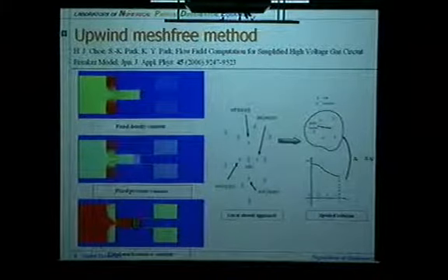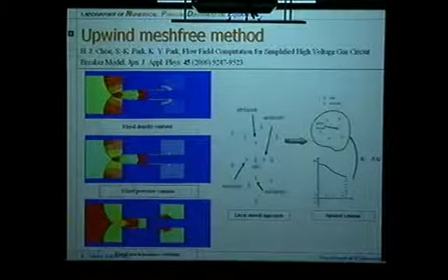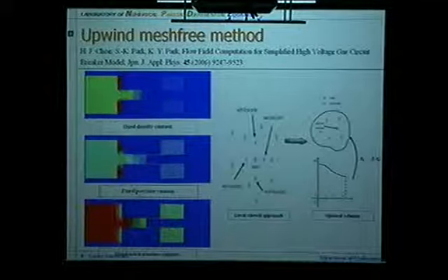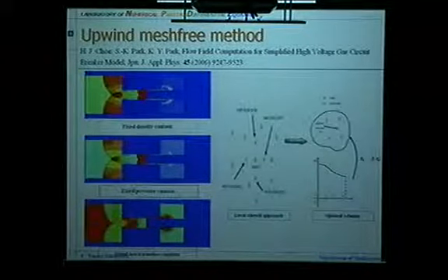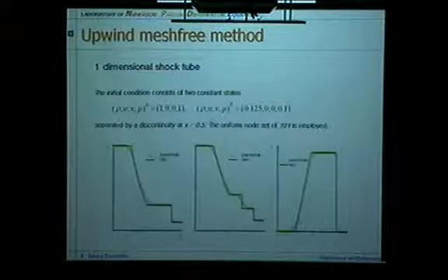That's the difficult part. So for moving geometries, the idea is, well, you just forget about the mesh. You just consider some nodes, generate the nodes, and let the nodes move. So we took the mesh-free schemes. Mesh-free scheme means we do not make a mesh. We just consider some element basis, and let this basis function follow.